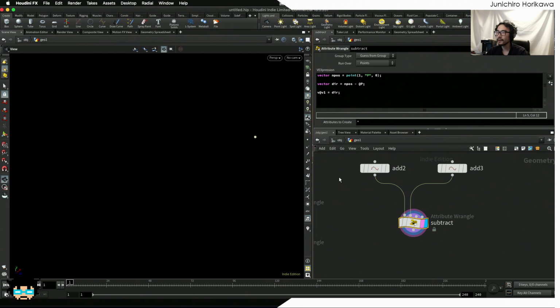Okay, seems like the point that I have inputted was right here, so I think I should look at it like this. Okay, so this was the second point and this was the first point, so this should be the B point, this should be the A point. Now let's try to show the marker by clicking this one. As you can see, if you also try to show the wireframe of this point, you have just created the directional value going from A to B like this. So you have successfully created the directional value.